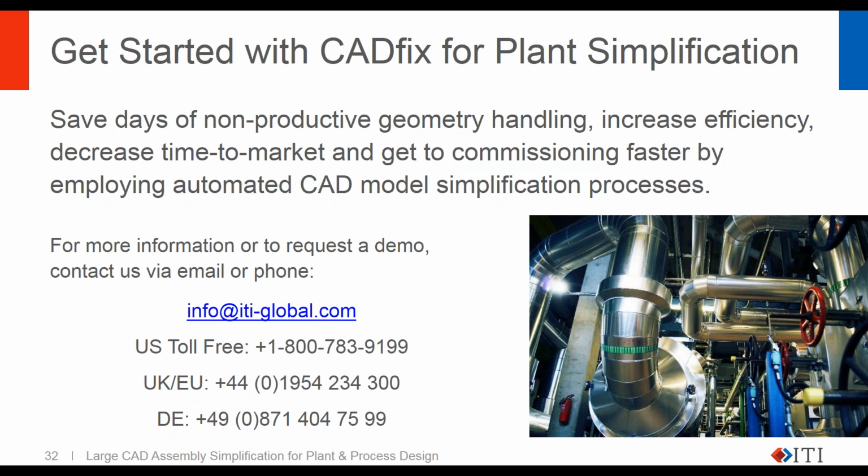It was hundreds of megabytes where every JT triangle was a CAD face. We did some reverse engineering work to read those faceted solids from JT and turn them into CAD solids that could then be simplified. It's not what I was presenting today, but it is something that we can do, processing faceted geometry into a simplified form. Okay, very good.